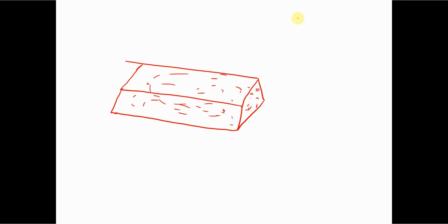And the runner is already filled, since we have a down sprue here, and the molten metal has been switched direction through this sprue well to fill into the runner, and the runner is completely filled. So what we basically do is make a little opening here and another opening, for example.